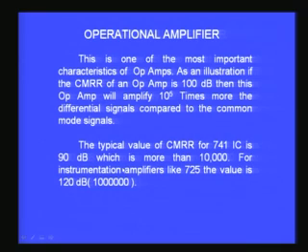There are some amplifiers called instrumentation amplifiers, which are meant for very low level signals. When you are trying to amplify very low level signals in the microvolts and nanovolts range, you would find the noise voltages can also be of the same magnitude, and therefore they can really harm the signal at the output.